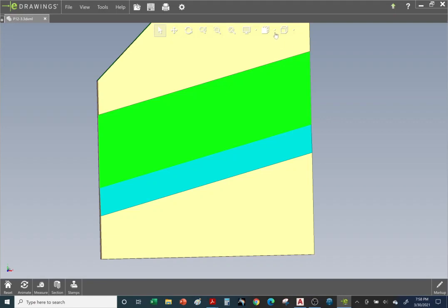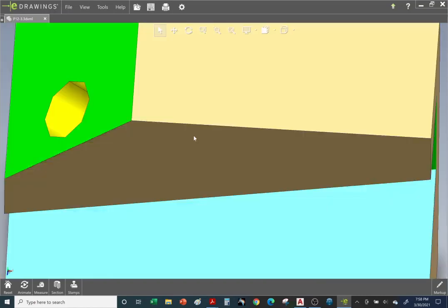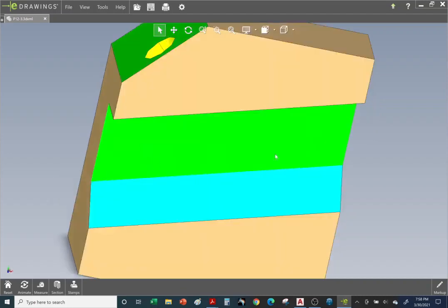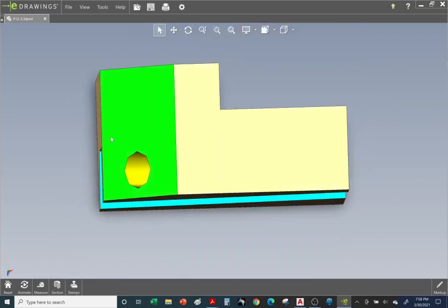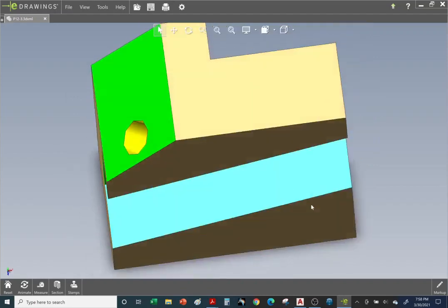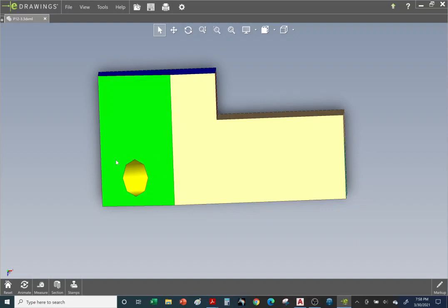Take a look at the 3D model. Top view. From the top, we need to draw the hole and also the exit. We need to draw this line, and we also need to represent the slot. From the top view, we cannot see this slot here, right? Can't see it, so we need to represent it with the hidden line going across. Let's take care of some of this geometry first, like the red hidden line for the slot going across, this object line, and then we'll come back and take care of the hole. That's a little bit more challenging.